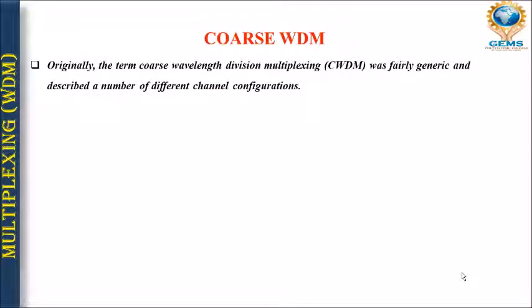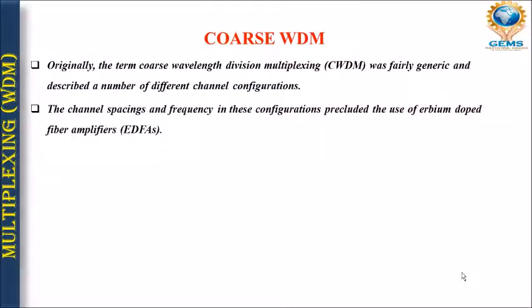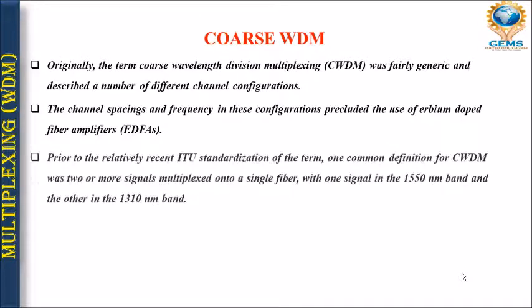Okay, so originally, if you talk about coarse WDM, it was fairly generic and was described in a number of different channels and configurations, right? Okay. Next, the channel spacing and frequency in these configurations pre-included the use of erbium doped fiber amplifiers, also known as EDFAs, right?